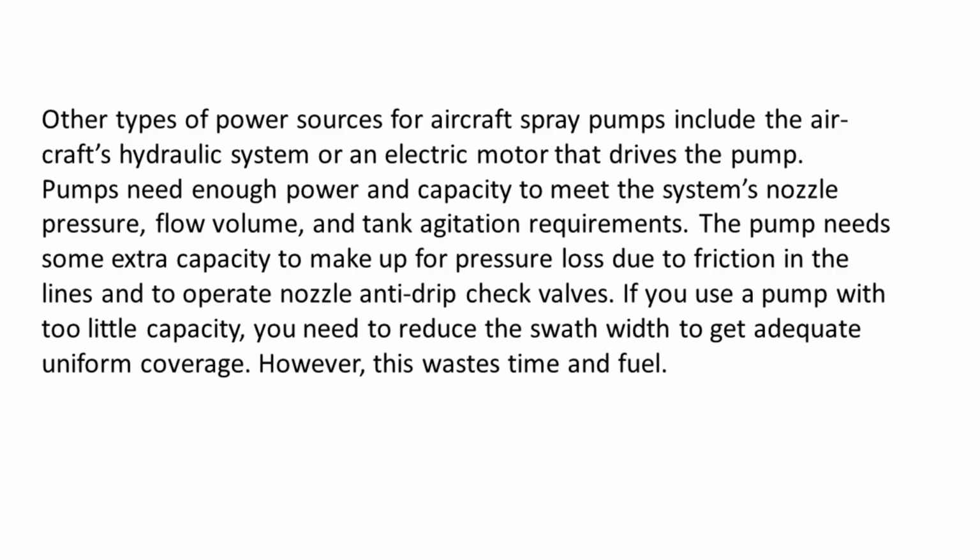Other types of power sources for aircraft spray pumps include aircraft's hydraulic system or an electric motor that drives the pump. Pumps need enough power and capacity to meet the system's nozzle pressure, flow volume, and tank agitation requirements. The pump needs some extra capacity to make up for pressure loss due to friction in the lines and to operate nozzle anti-drip check valves. If you use a pump with too little capacity, you need to reduce the swath width to get adequate, uniform coverage. However, this wastes time and fuel.